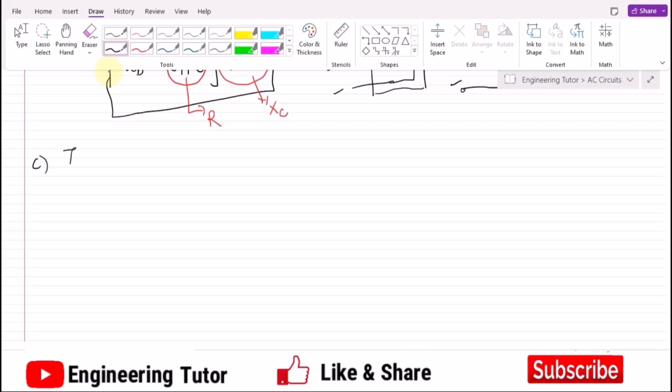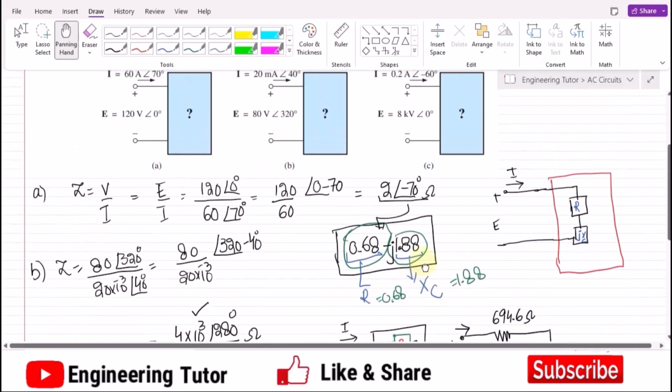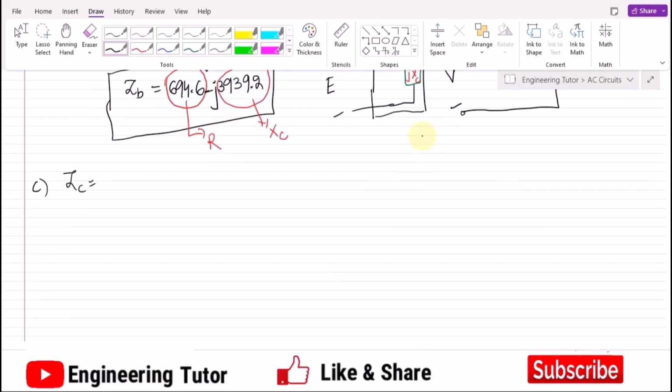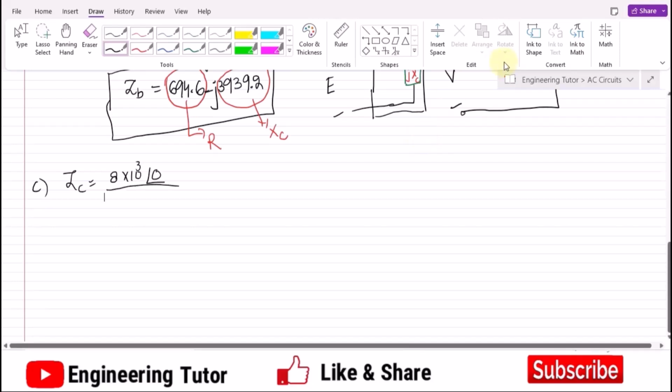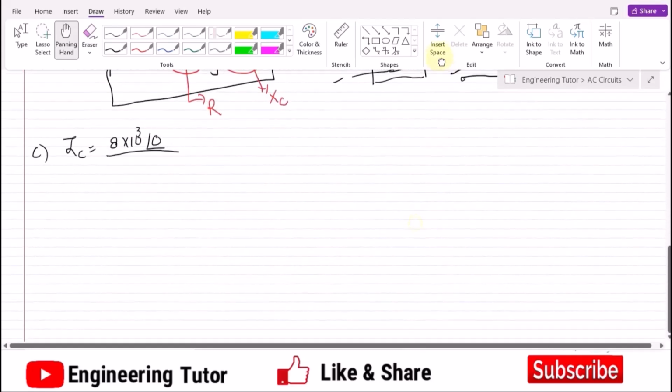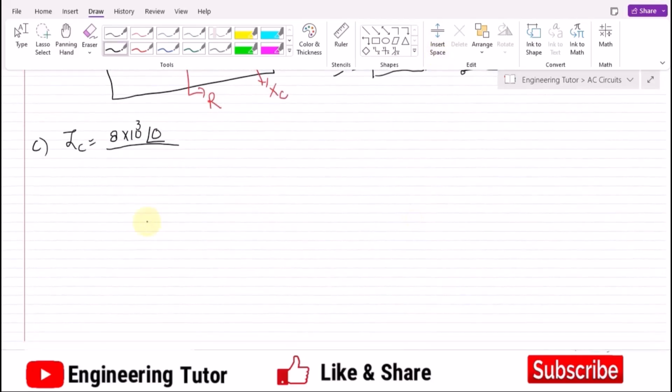So for part C, Z of C is again V by I. The value of V here is 8 kilovolts with 0 degrees, so 8 into 10 to the power 3 with the 0 degrees angle, and divided by the current. The value of current here is 0.2 amps with the minus 60 degrees angle, the phase of minus 60 degrees.